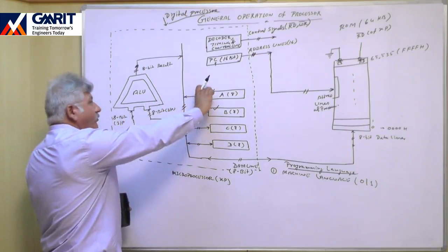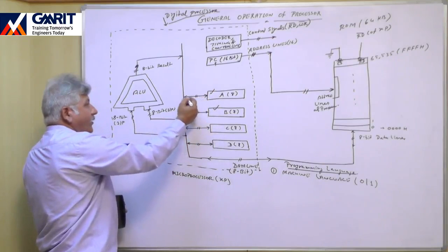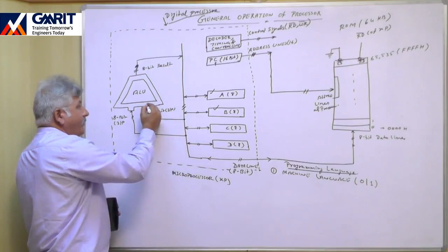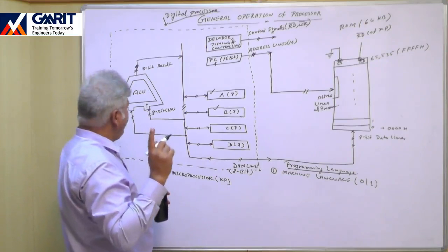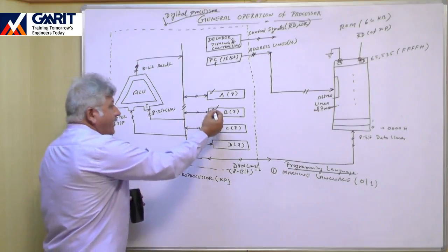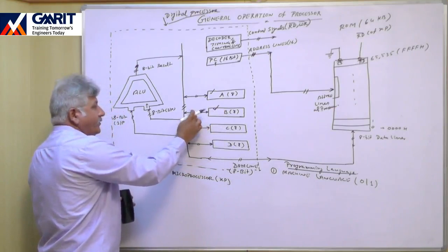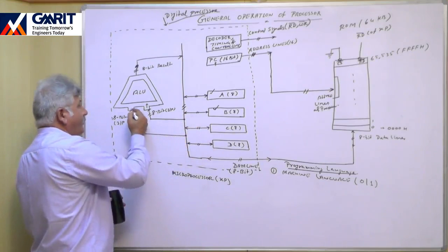It will bring out the 8-bit number which is in A through this data bus and it will be available here to this ALU as the first number which has to be added with the second number. Now the second number is in B, it will come out from this 8-bit data bus and from here it will be available to this ALU as the second number.